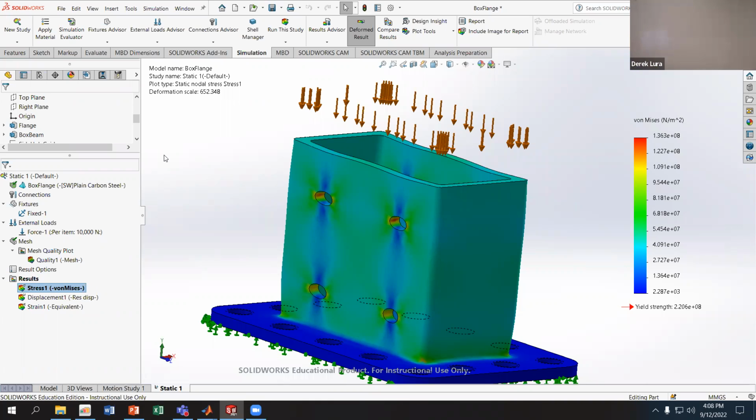You care about the stress distribution and the direction of the stress mostly when you are changing the geometry of the part in some substantial way that is going to change how it responds to different loads. So this is probably not the best example because that loaded stress is very simple, but we can change this to have other stress distributions reasonably easily.